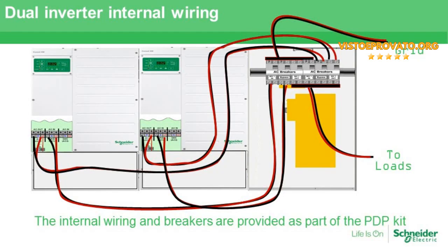When looking at the basic building blocks for an AC coupled solution, you do want to check with the manufacturer of the inverter to make sure that it is compatible with frequency shifting. But one of the nice things about the XW Plus is that with frequency shifting, it will finally kick out at 60.5 hertz. But ideally, an inverter will actually listen to the frequency shift and actually diminish its output so that we get more of a controlled charge based on loads and as well as whether or not the batteries need any charging or whatnot.